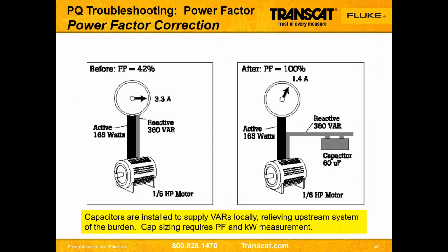So many folks use what is called power factor correction. This is a way of installing capacitors on the electrical system to compensate for a system that's very inductive and make it more capacitive and bring it back to a closer, what we call unity power factor, which is the equivalent of being 100%. Honestly, the only thing that's ever really been 100% in the last number of years is the incandescent light bulbs. But of course, we just threw all those away. Those are no good anymore.